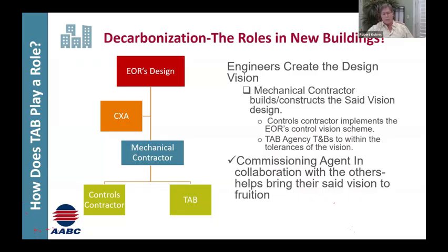Right, and I was referencing performing that balanceability review, and this is an example that just happened recently. I was performing this review, and you check out the air handler equipment schedule, and the column for the chilled water coils, the GPMs tallied up to, we'll say, 1600 GPM, and it's a variable primary system, and there were 3 chilled water pumps in parallel, 600 GPM each. So I'm approximating 30 to 40% diversity in the system, which is quite a bit, but that's only where it began. It didn't end there.